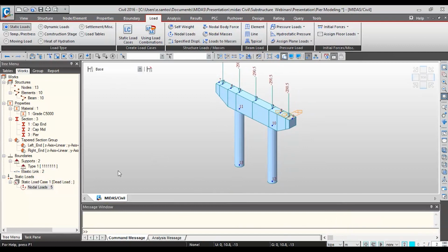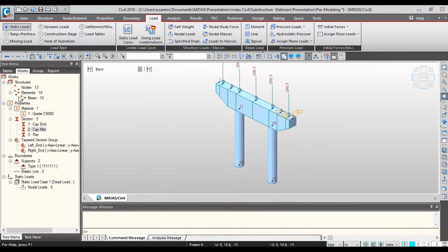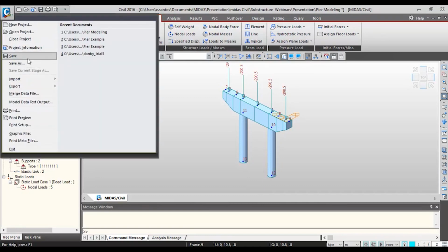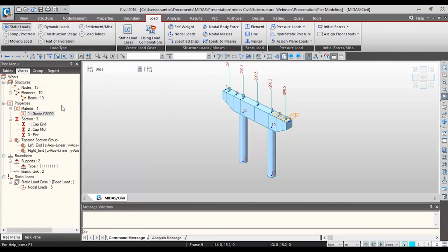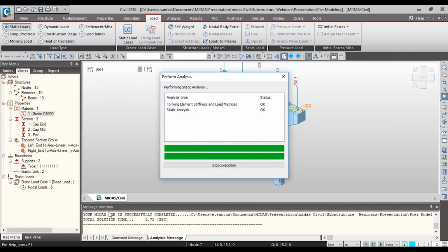After that, you can also see the different types of supports that you have applied graphically. You can see the sections, you can modify them if you need to right here, and so on. You can also add directly from this worktree, so it's up to you how you want to use the program in that matter. So from there, I'm gonna save the model. You can easily come just to save it or save as, and then you locate the model, and then you can easily just run it and see the different types of values that you can get.